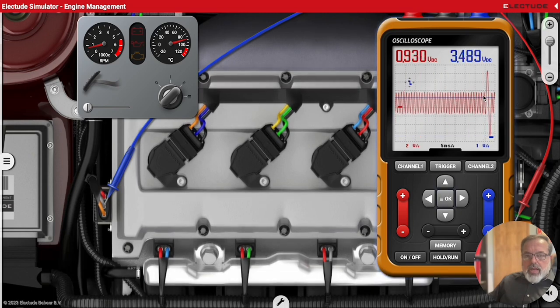Now of course here again we got a very random screen because my trigger is set too high, so we need to lower that voltage. So now we're triggering off the, and we're on a negative slope. You can see we're on a downward slope. Let's change that to a positive slope.